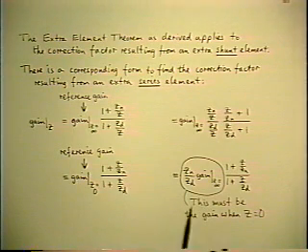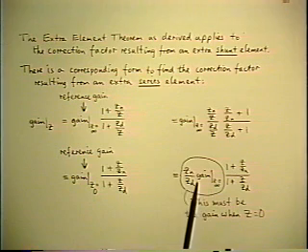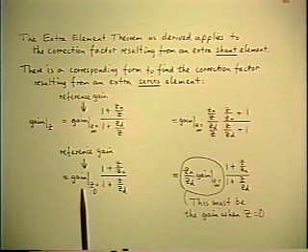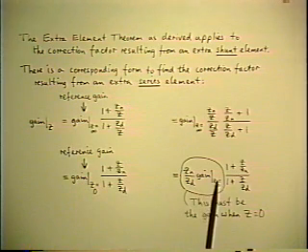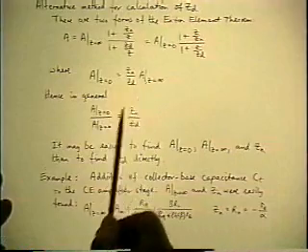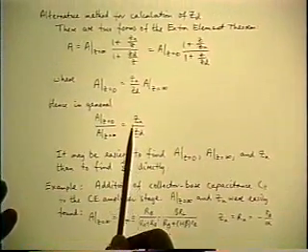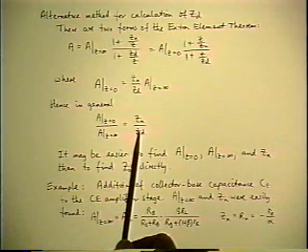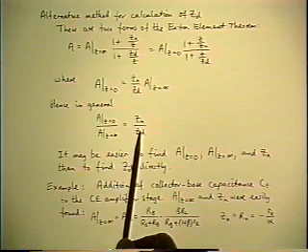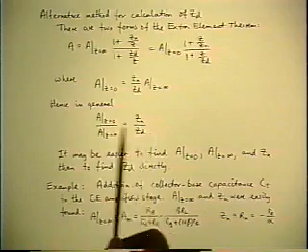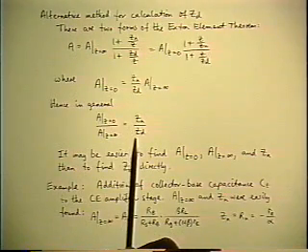Now there was one aspect of that that we weren't concerned with at the time, but we can now use. Namely, the definition of the gain when the extra element is zero is that it's the gain when the element is infinite multiplied by the ratio of the two driving point impedances, which is this, or rewritten in a symmetrical form, this part of it. This is also the dual of the frequency response interpretation: the ratio of the two flat gains is equal to the ratio of the corner frequencies that separate them. This is the same thing where the variable is impedance.